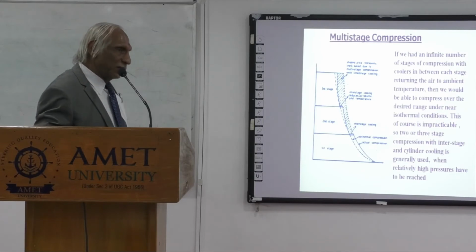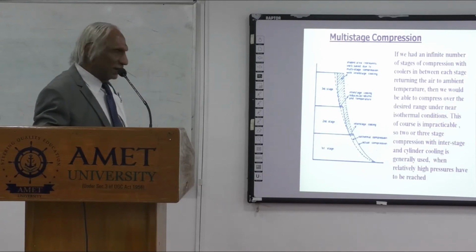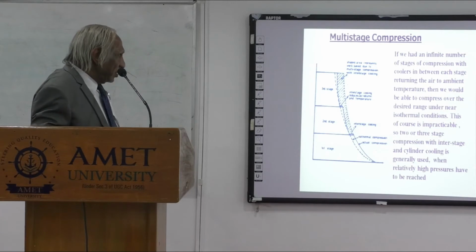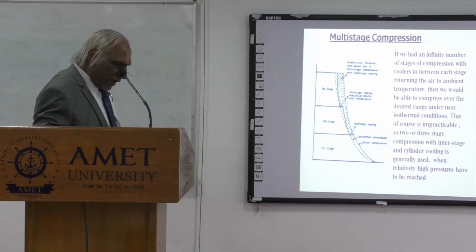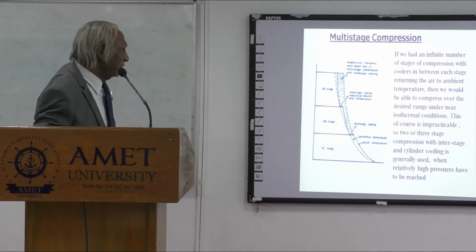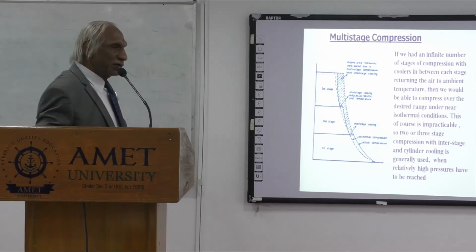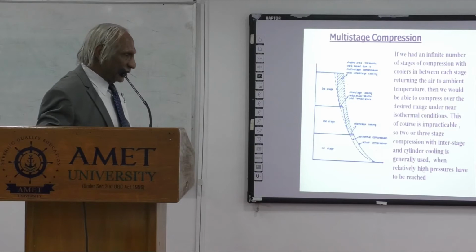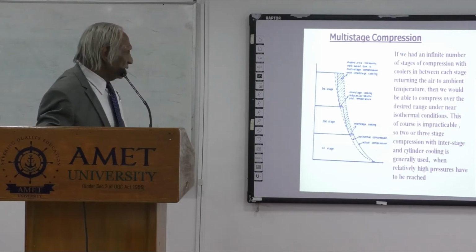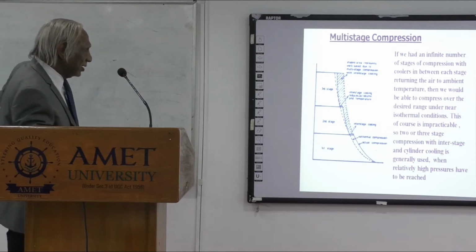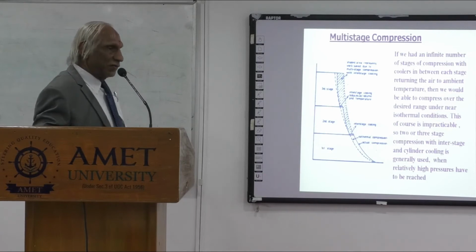Now, as a human being, it's not possible for you to climb a single staircase right to the third floor without taking a break. In the same way, it's not possible for the air compressor to compress directly from atmospheric pressure to the final pressure, let's say 30 bar or 120 bar, which is usually for off-road drilling vessels, and 30 bar usually for ships. So this final compression pressure can be achieved only in stages.